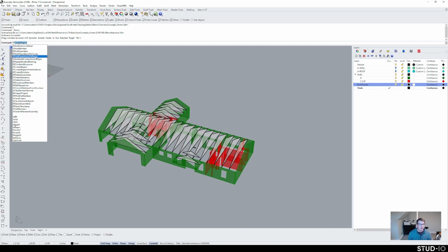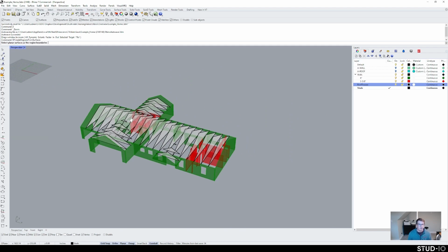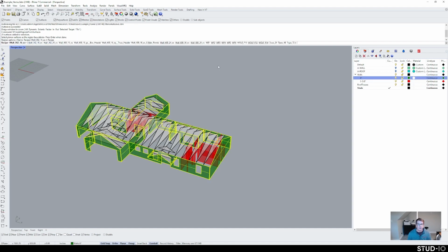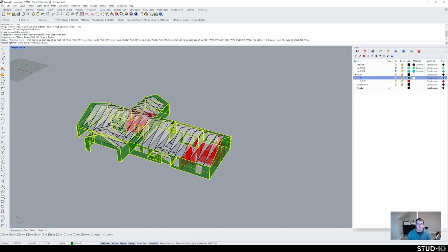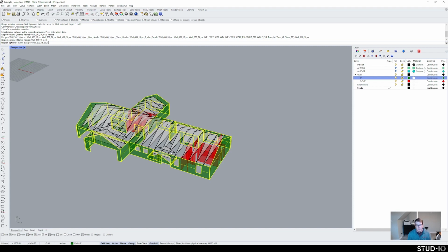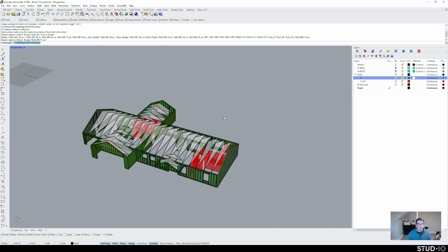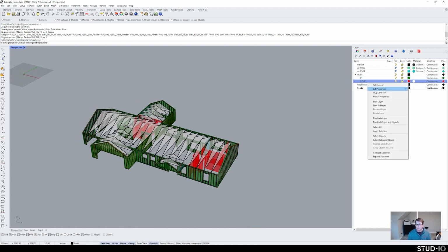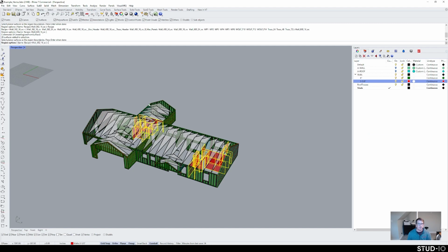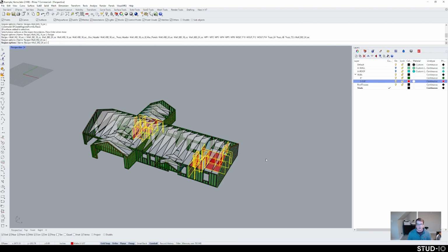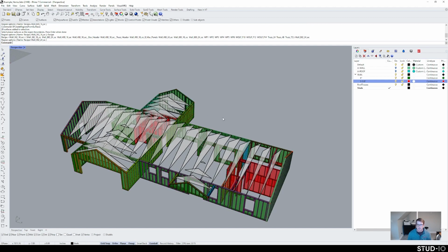Using that SF create region from surfaces, I can select all the 6-inch walls, apply a 6-inch 16 on center recipe to that. It takes a second to generate. You'll get all the framing for that. SF create regions on surface, grab all the 3 5/8-inch walls. Let's generate 24-inch on center spacing for those, because interior walls, maybe they're not load bearing, don't need 16 inches on center.